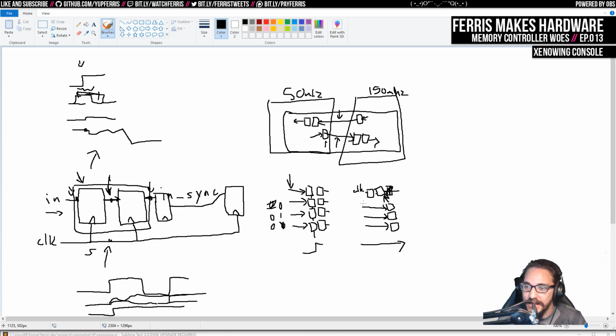And so the idea is that if all of this changes at a similar time, these will have an extra cycle to settle. And this is actually okay, because you won't sample these values. So I think actually I'm drawing these wrong, and that this here should actually be some kind of gate where you have the input and then an enable. And the enable comes from part of this stuff that's inside this clock domain already.